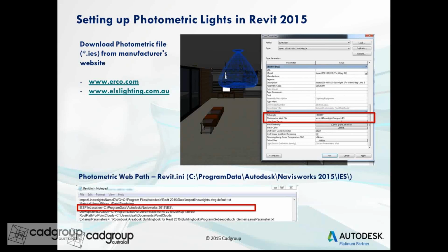A lot of people registered cases with me about not having artificial light properly rendered, or it doesn't render correctly, or it doesn't have, I can say, the desired effect in the rendering. So the answer was the missing IES file. That means it was not properly configured.